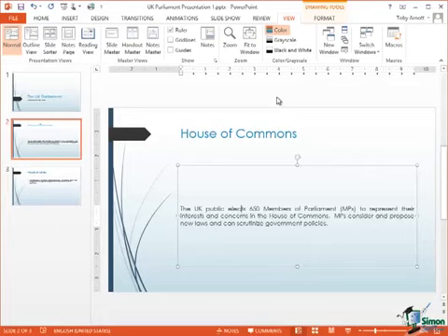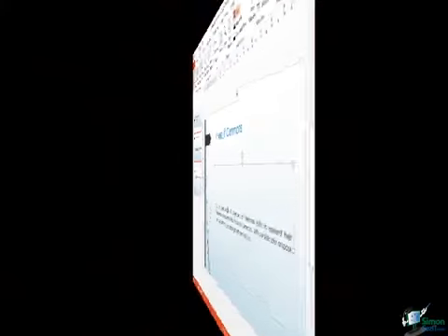So in this case, my machine's set to English United States. The units I'm using are inches. If I wanted to work in centimeters, I would have to go into the regional settings in Control Panel, in this case in Windows 8, and change the settings to metric from inches. But for the moment, I'm going to assume we're going to continue to work in inches.